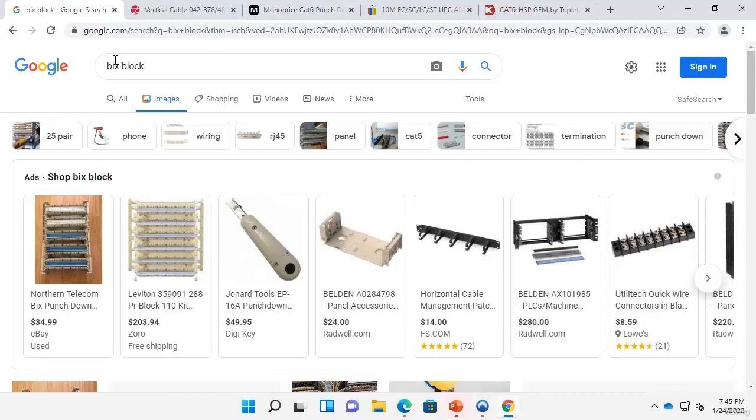You don't need to know the differences between those. It's just a couple of different styles for the same concept, a punch down block where the wires from the wall jacks are terminating. The most important part of that is probably just all the terminology. But like I said, I wanted you to actually see some of that LAN wiring, or the LAN wiring components, I should say, just to hopefully make it a little bit clearer.